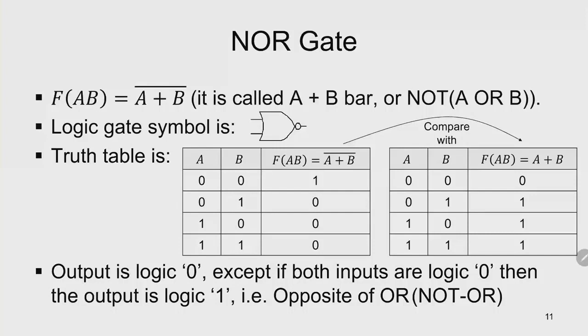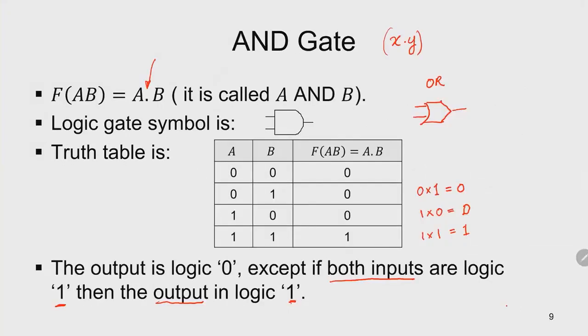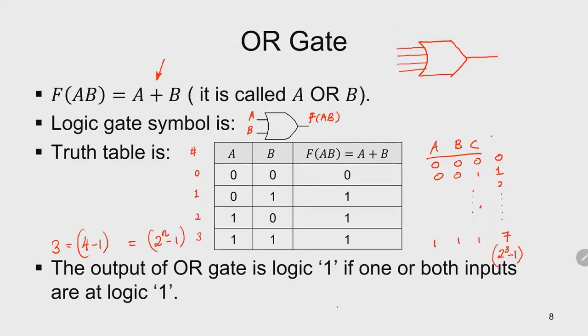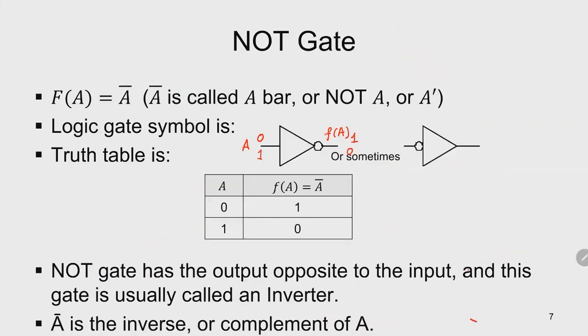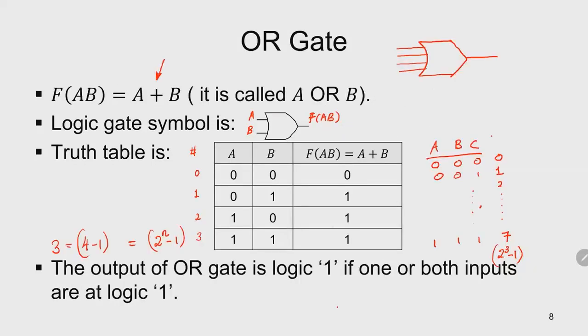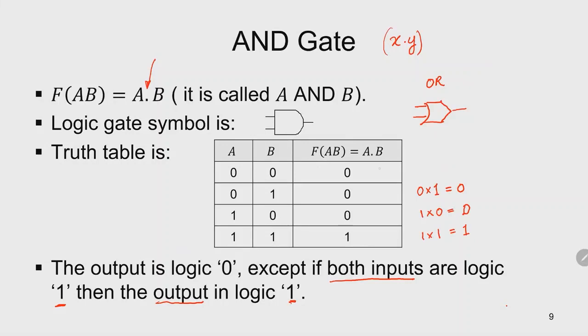Okay, if you know all these gate truth tables, then you have a sound foundation in digital electronics. There is no other way except to remember the truth tables. You have to learn that by heart. In actual fact, you only need to learn 3: the NOT gate, the OR gate, and the AND gate. And the rest is a derivation of this.